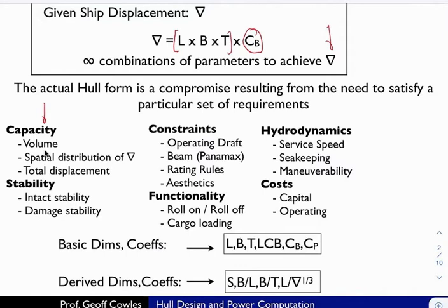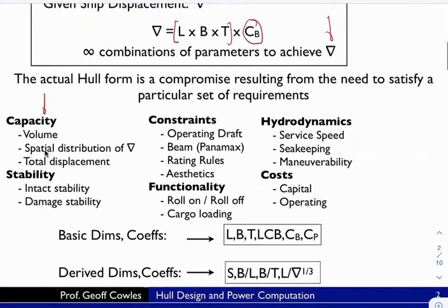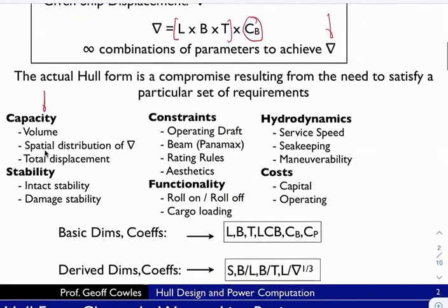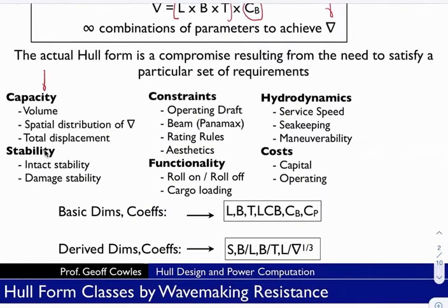If you're dealing with racing boats, sailboats, or powerboats, often there are rules that are applied. They can be simple rules like a box rule, whereby your boat essentially is to fit in a box. It could be more complex rules that devise relationships and implicit trade-offs, for example, between length and sail area. In sailing that is quite a common rule relationship. And of course, aesthetics. If you're working with a client, they might be looking for a certain look to the boat, and that can, for example, a traditional sailboat with long overhangs, drive the actual geometry of the boat.